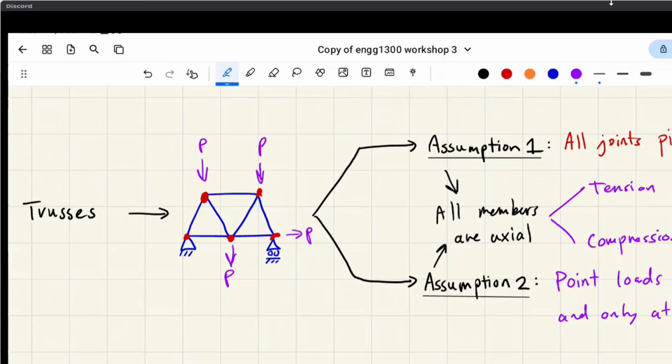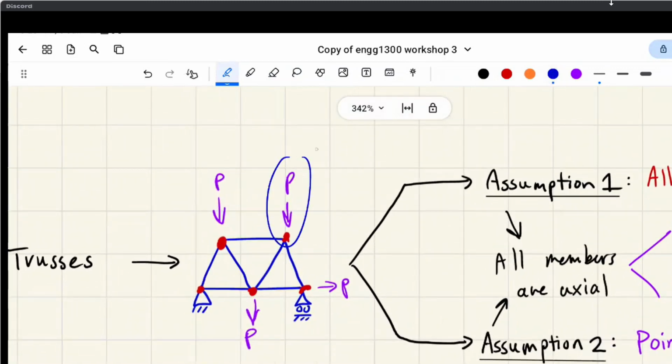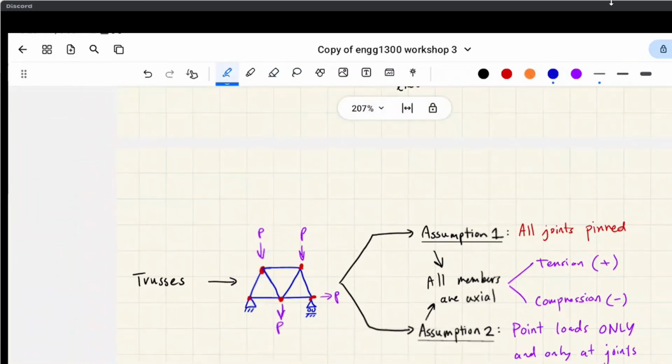And from now on, we're just going to assume tension conventionally is positive and compression is negative for our method of joints specifically, right? But this is a good way to remember it, right? And that just means that this load here is going to go into this diagonal member, and we're only going to consider the compression for that. We're not going to consider any shear, so if we have a point load there, it's going to create shear force, which we don't want.